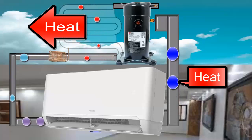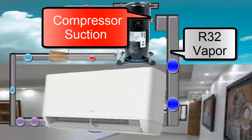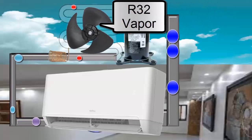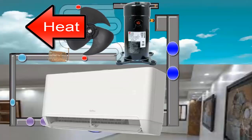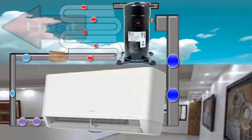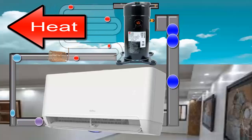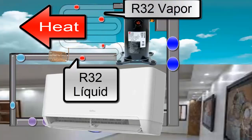To achieve the operating cycle, the compressor sucks in the R32 gas in vapor state and takes it to the outdoor unit, condenser. In the condenser unit, the R32 releases heat into the environment. To improve this process, the compressor increases the pressure of the R32. Due to high pressure, as the R32 releases heat, it changes from a vapor state to a liquid state.